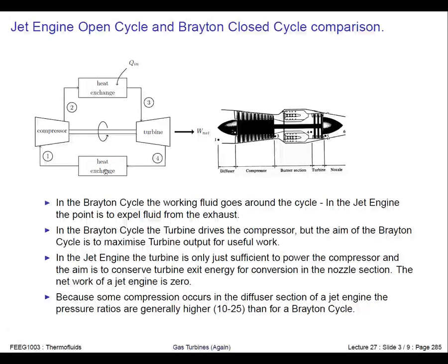So this is the Lagrangian way of doing energy conservation using the system. We take a little mass of air and follow it around this system, and we look at the energy transfers. Based on these energy transfers we can work out the efficiency of our cycle, and we can do that by drawing a big system boundary around the whole thing.